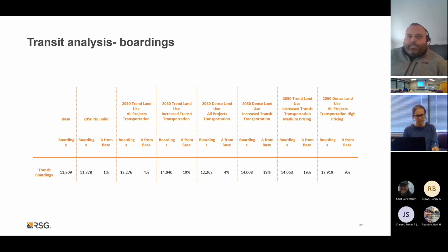Like those routes might just purely not exist. So if we want to do route level calibration results in the model, we need to have an OD survey that matches the routes. In this case, where we didn't have an OD survey that matched the routes, we couldn't calibrate the routes anymore, because we would calibrate to the OD survey results, or the expanded OD transit onboard survey. So all we could do is take the boardings that we had, the system level boardings, and calibrate to that.